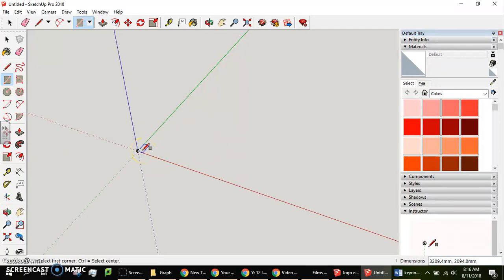Okay, so now I'm going to go back and you can see again that it's snapped onto the origin. I'm going to click once and drag out, and then I'm going to type in 100. Now notice as I'm typing in 100, this is coming onto the bottom right hand side of the screen. I hit 100, comma, 100, and then enter. Now it may seem really small on the screen, but in actual size, it is to scale.